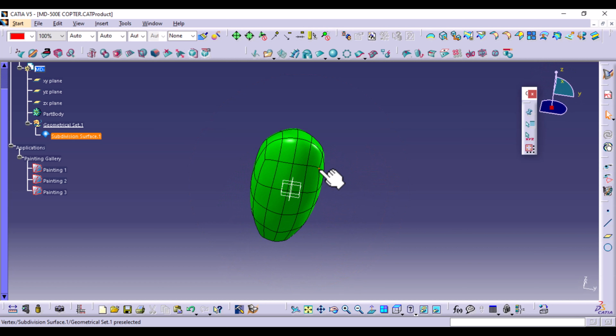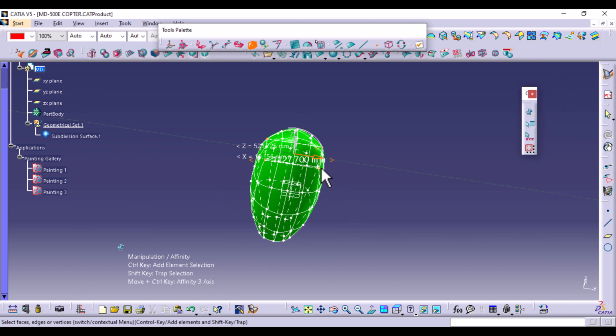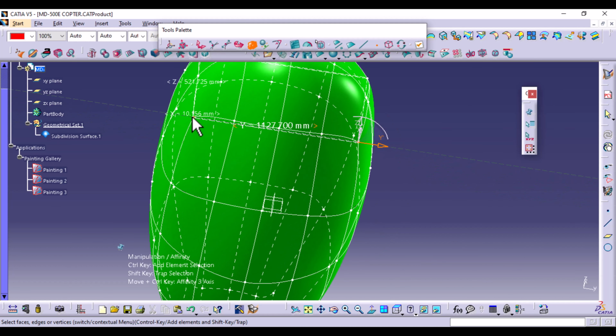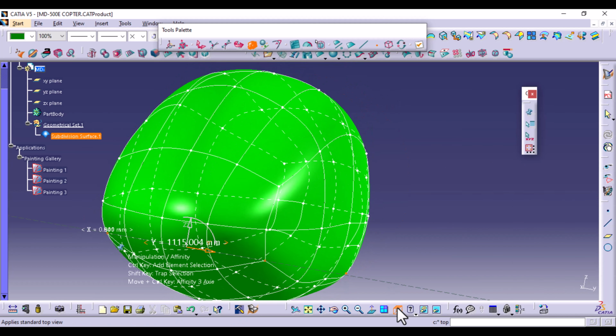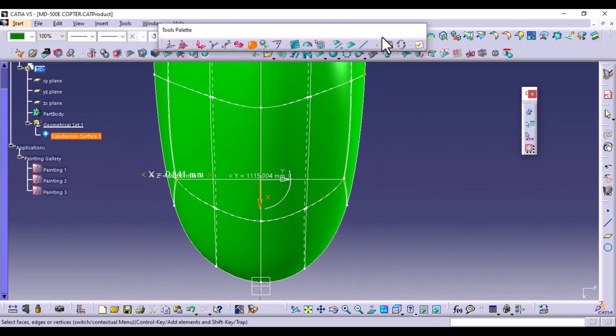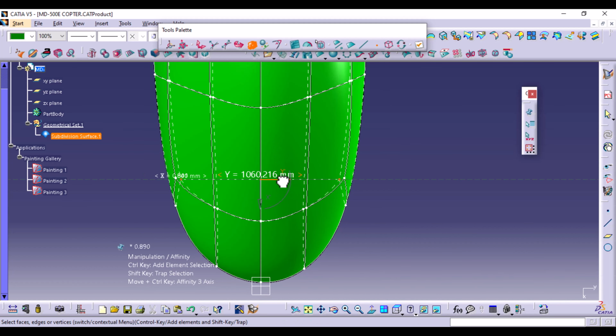For example, these two vertices at the bottom, you select this vertex and this, control this vertex at the bottom, again top view. You can pull them inner instead of aligning them with the top ones so that it's kind of tapered downwards at the bottom.